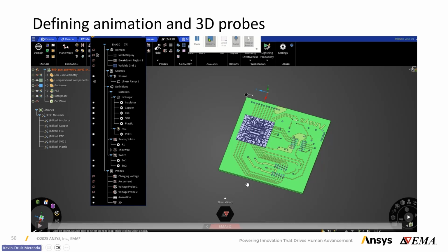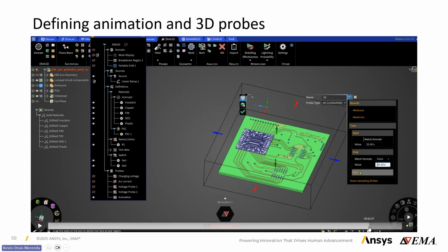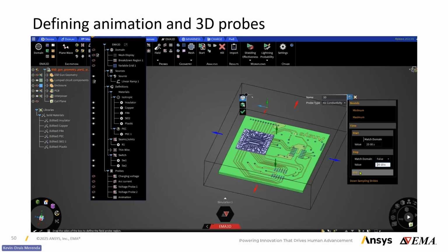It is a lot more data. So when you set up the probe, I think you want to make sure that you look at the time step that you're using and the range of the data that you're saving in terms of computational time domain. So instead of saving, for example, the full microsecond of simulation, you may save maybe 10 nanoseconds in the time where you expect the discharge to occur, or maybe based on the breakdown voltage that you got from the previous simulation, to be able to look at where the ionizations occur.